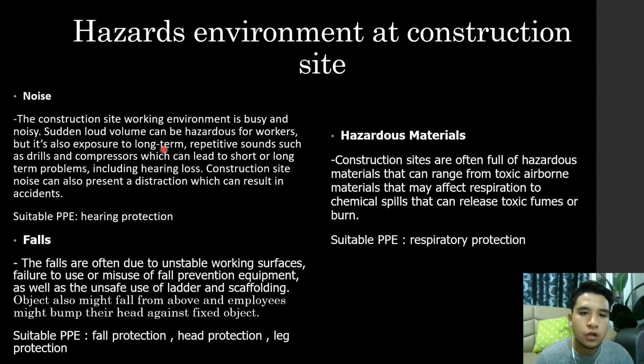Sudden loud volume can be hazardous for workers, but there is also exposure to long-term repetitive sounds such as drills and compressors, which can lead to short or long-term problems, including hearing loss. Construction site noise can also present a distraction which can result in accidents. So for this hazard, the suitable PPE is hearing protection.